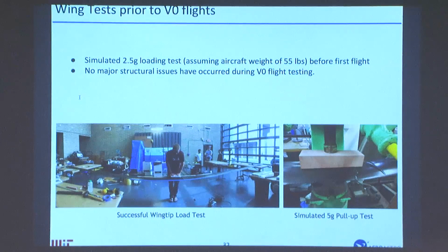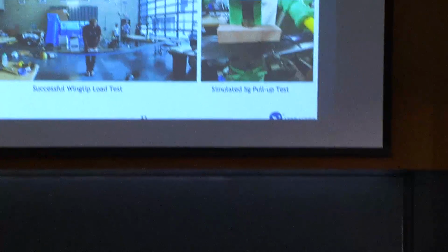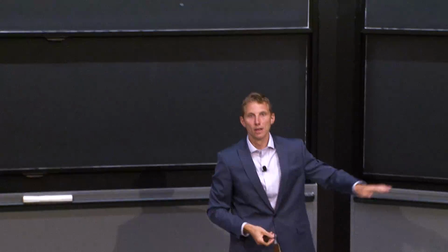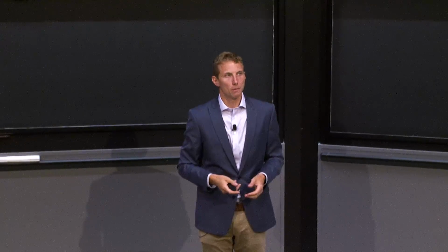In the real airplane, the loads are distributed because the lift on the wing is distributed from tip all the way into the root. So you have a distributed load pulling up on the wing, and then you have a point load of the fuselage pulling down in the middle. And you can do the math and figure out what the bending loads are.